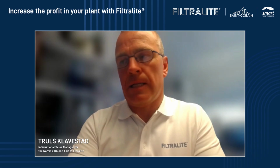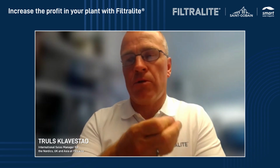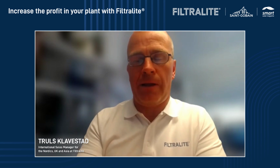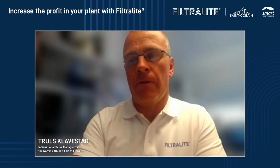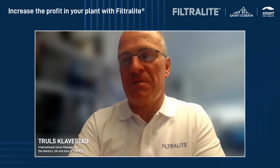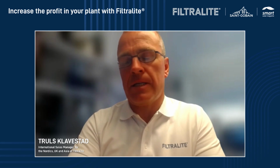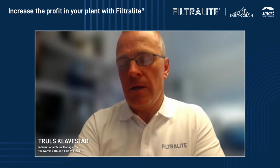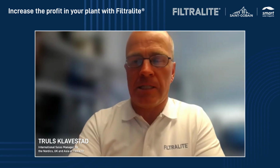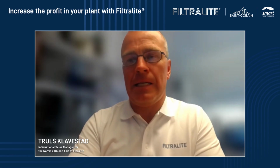But we have also seen that sometimes when you have a lack of oxygen in the water, we still come nearly down to a non-detectable level with iron. We should maybe have done a PhD to really understand what's going on with this kind of biological filtration, but it just works. Especially, as I said during the presentation, iron is quite easy to remove.